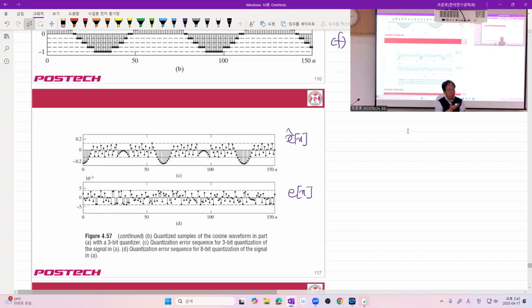Of course, in the time domain, first, what? The histogram of each sample, which corresponds to the first order PDF of the random process. And then you may consider the second order PDF, and that's too complicated. So what do they do? They calculate the autocorrelation function of the random process. After you compute the autocorrelation function, the next method would be to Fourier transform it, which will give you the power spectral density.